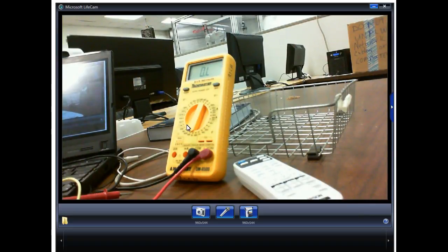And why is that? Because we input on the emitter, and the emitter carries how many currents? 2 currents. So all the emitter current does not get to the collector, which is where the load is. You have to take the base current out. So common bases have a current gain of less than 1.